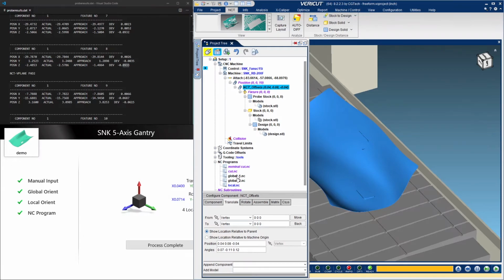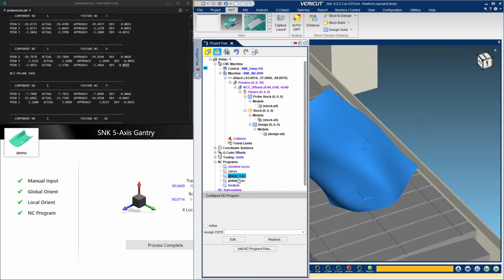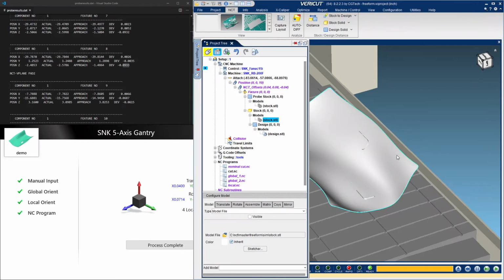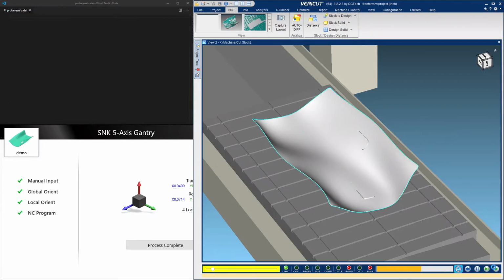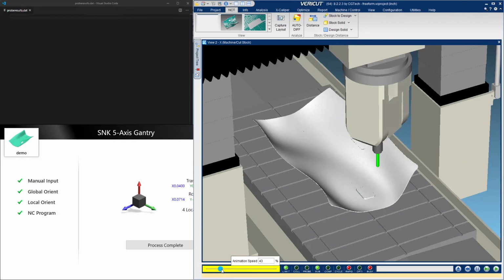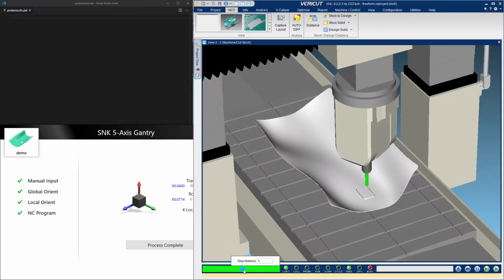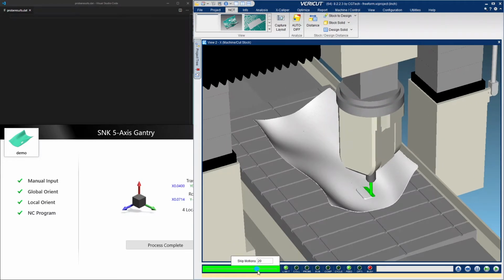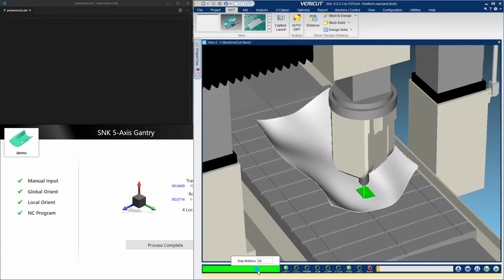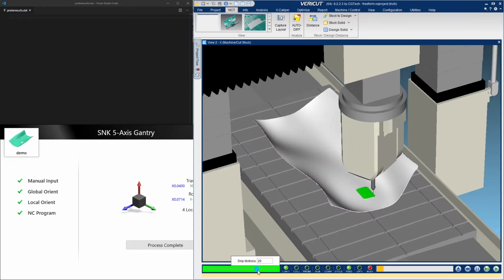Now the only thing left to do is to run our transformed cut program. To do that, we'll go ahead and turn off this special probing stock. We'll turn our stock model back on, and we'll run that cut program. Then we'll do an auto diff to ensure that everything went smoothly and as planned. We'll speed this up a little bit, color the top surface of those pads. And then when that's done, we'll use our 1/4 inch ball end mill to blend in that pad surface with the existing contour.